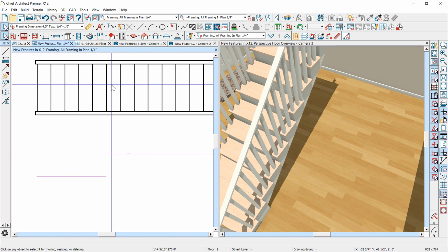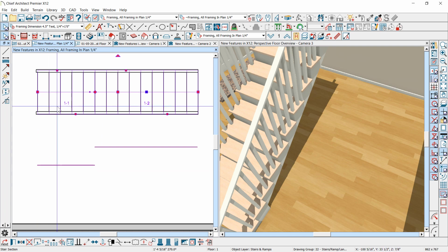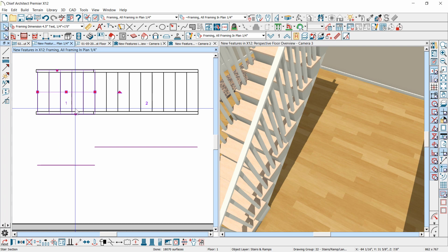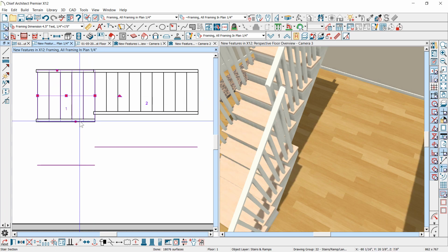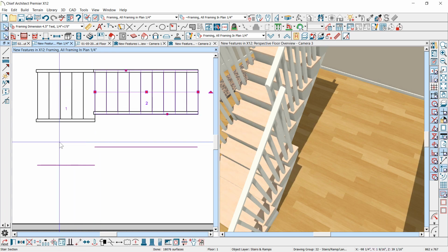That's what we're doing to the stair. So I'm going to click on that stairway. I'm going to click on the part here, and I'm going to click the separate line tool, and now I can separate this and pull that apart separately. You see how the center of this stairway, where that line is moving now? Okay, just like this right here. We're separating those two lines. So that's how you make stairs wider that are already hooked together, and that works really well.